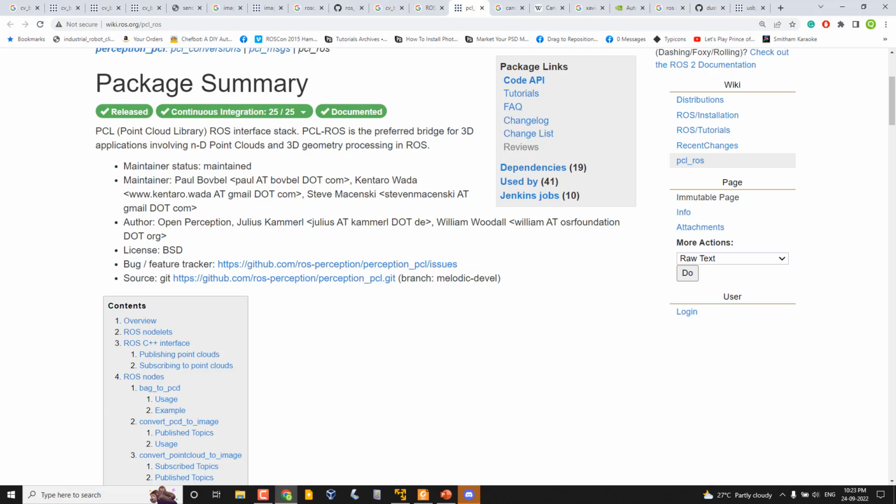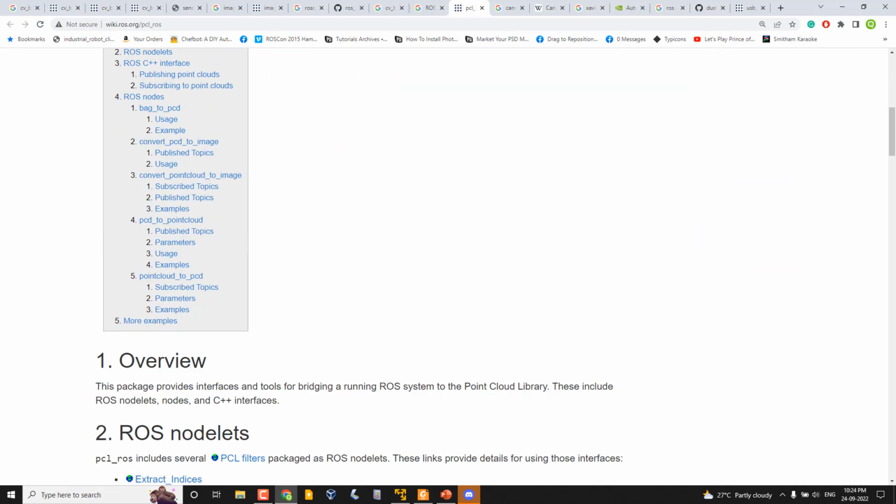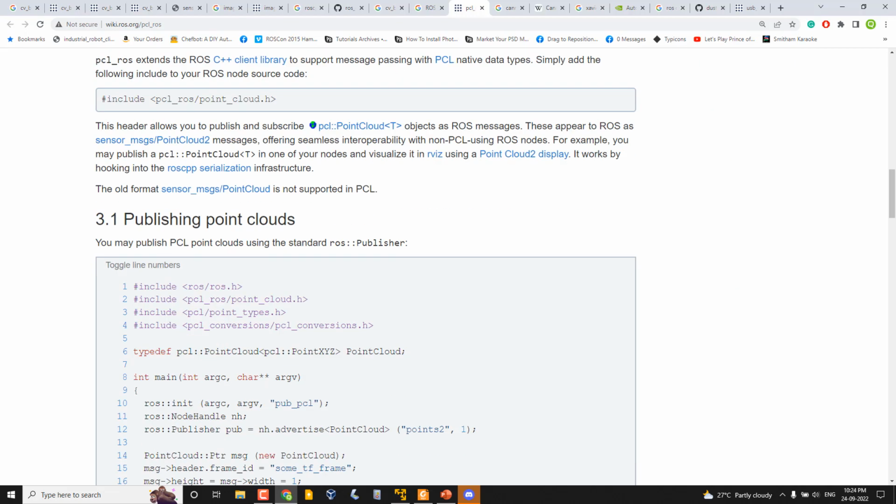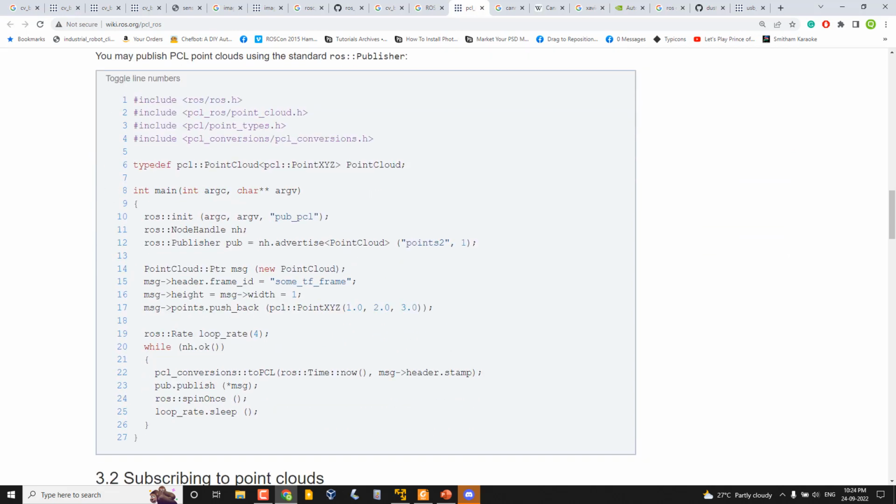Not only the processing, the reading of these points from the depth sensor itself is a hectic job for the CPU. It has to read from the IO, and the bandwidth will be very high. It has to read from the LiDAR or the depth sensor, and after reading, PCL has to process the data, maybe filtering or segmentation.